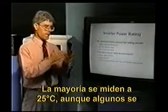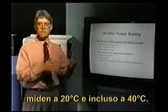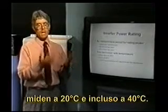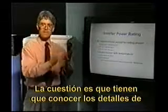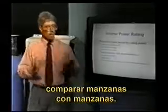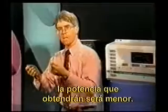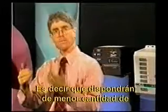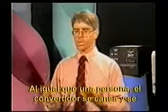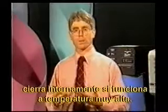Most inverters are rated at operating at 25 degrees C. Some are rated at 20 degrees C. Some are even rated at 40 degrees C. The point is, you've got to know the details of how the rating is made in order to compare apples to apples. If an inverter operates at a higher temperature, the power that you get will be less. The amount of time that you have to operate that inverter will be less. An inverter, just like a person, gets too hot and too tired and internally shuts itself down if it operates at too high of a temperature.